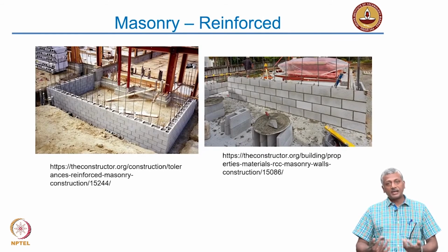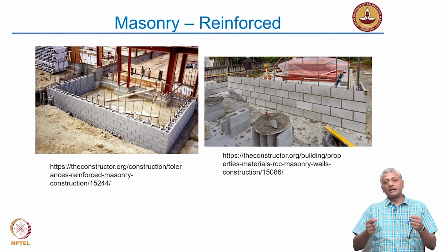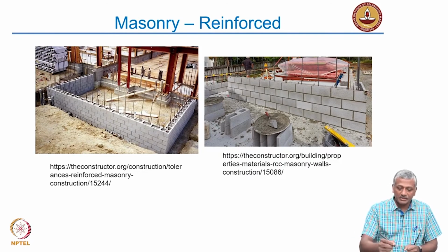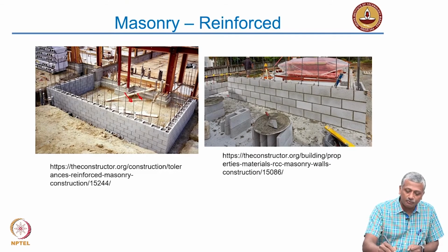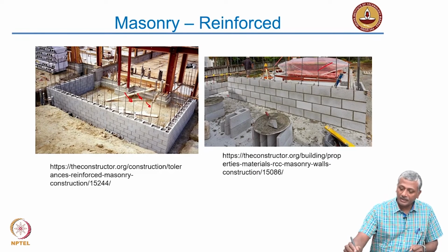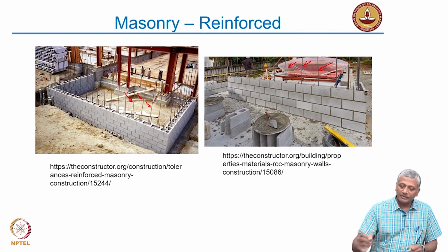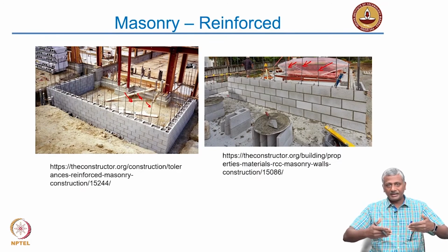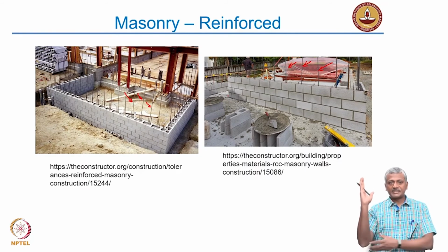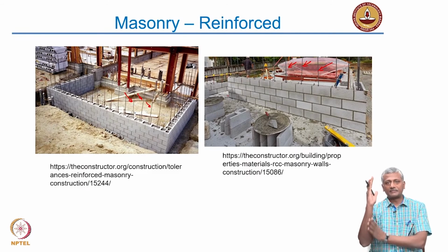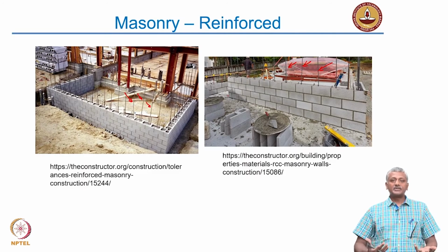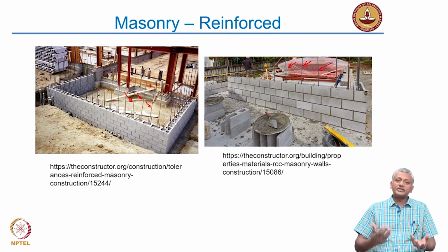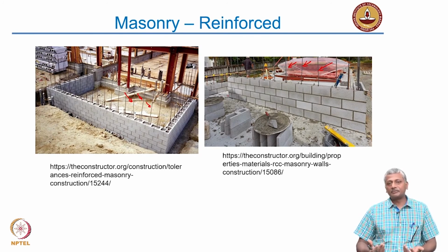Later, people realized you could produce masonry with concrete, and that led to the formation of hollow concrete units, and the hollow cavities were then reinforced with steel. The cavities inside concrete blocks were later reinforced with steel, so that now you could get a composite action out of the masonry wall, not just the compression load that it will take in plane, but also resistance to lateral forces because of the steel. So, we started utilizing materials and combinations of materials in such a way that they gave the maximum benefit.